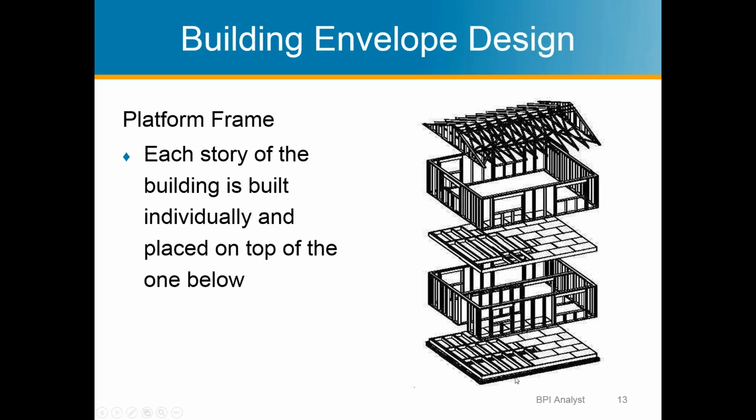And what that causes, from a building science perspective, is that if we assume this is a crawl space, the air from the crawl space can get into the wall at the bottom, go all the way through the first floor, the second floor, and the second floor wall, and then to the roof. When we're talking about stack effect, that's really the issue here: it's almost always cooler in the crawl space than the attic. So it's like having a chimney in the house.